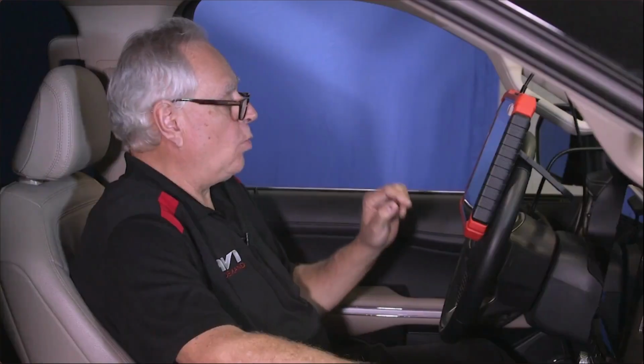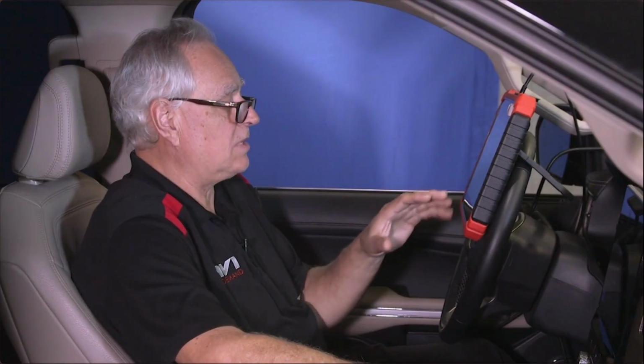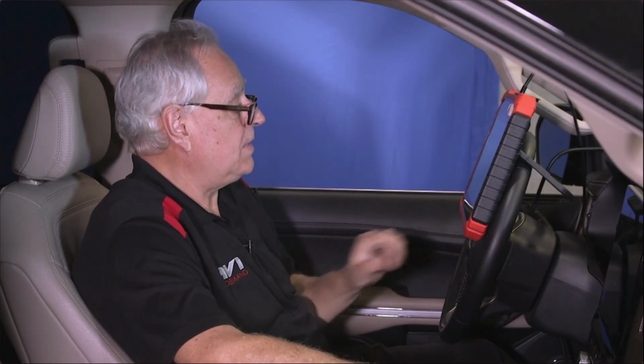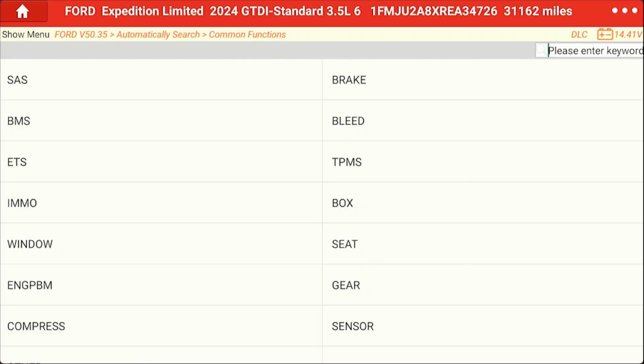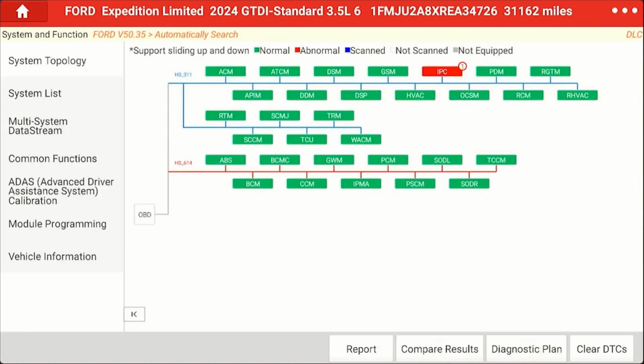This is awesome. When you're done, you also don't have to go through a procedure of hitting different buttons and switches that Ford offers on some applications to exit the park brake maintenance mode. What it does is it basically allows you to execute changing the pads, completing the job, and resetting the clearance on those electric parking brake calipers. So all this stuff is in here. Pretty slick. You've got the brake procedure. You also have bleed, etc. on here. So there's all sorts of stuff available. Seat stuff, you name it. Keys, everything is here.